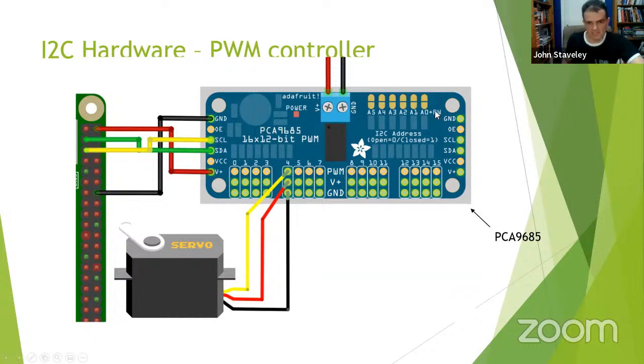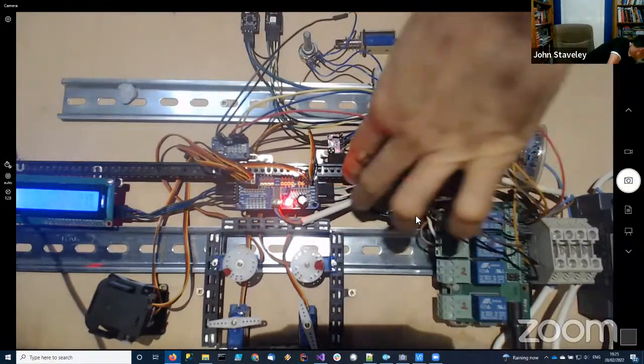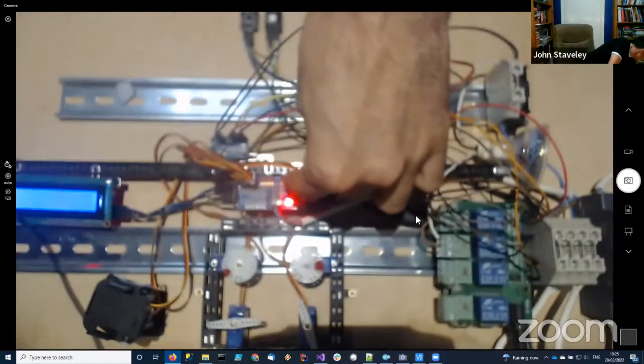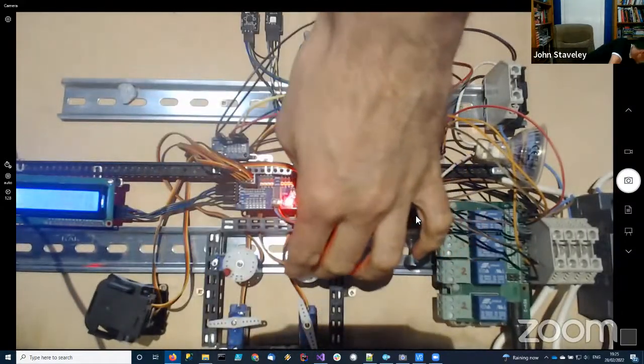And in fact, you can stack these 36 of these devices to control 36 times 16 devices if you want. Now, the Raspberry Pi can't deliver that much power, so you've got this supplementary power here. So that connects direct to your power supply. So here you can see it's set up. It's connected to my Raspberry Pi here. So positive, negative, standard data clock. And these are control. All these lines here are going to these devices over here. All these different PWM devices.